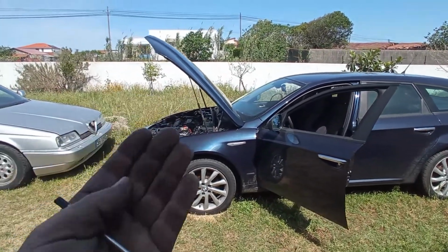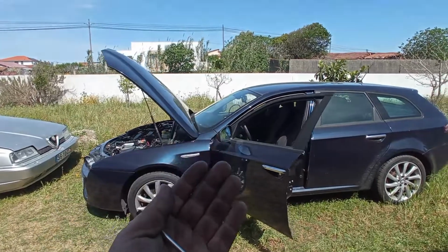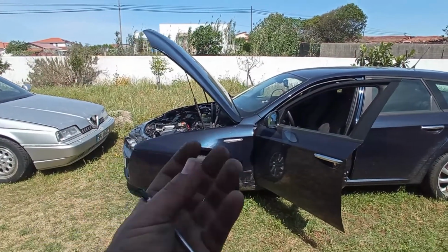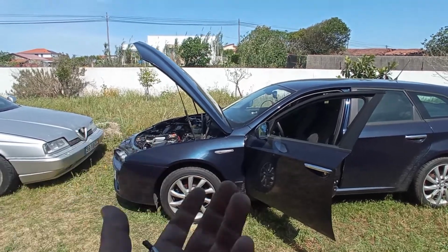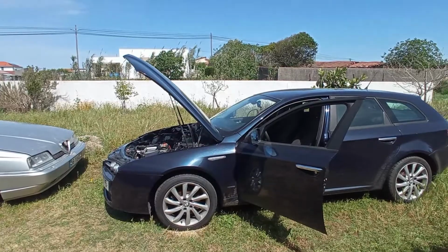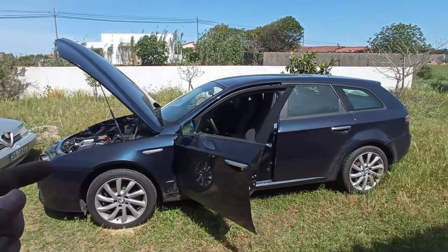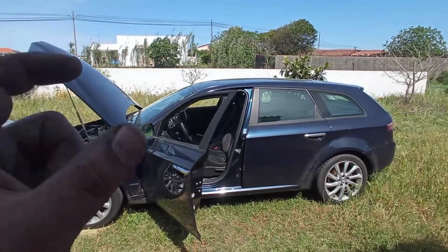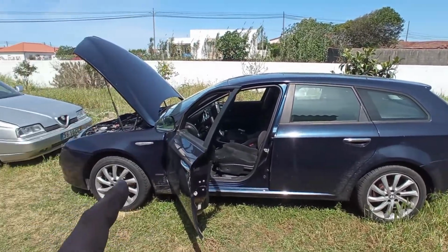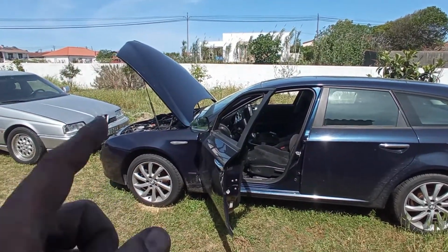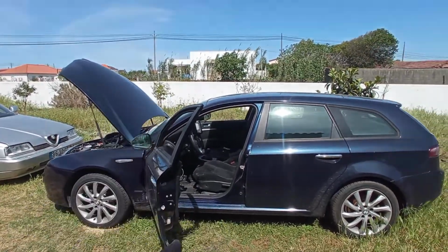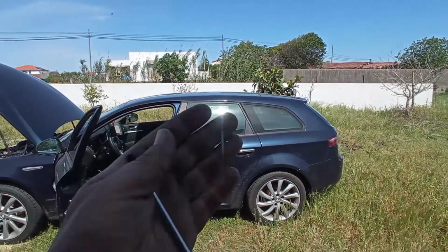Okay, deposit oil. Once you have a request for a regen, that can be aggravated because of the clogging of that carbon and oil on the exhaust. Now you have the temperature of the exhaust rising quite a bit, and then you have a burn of that oil while the car is doing a regen. The problem is not the regen, okay? The problem is the oil consumption of the engine that you now can notice while the car is doing a regen.